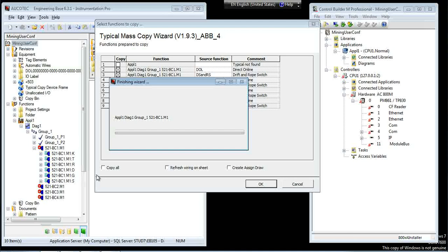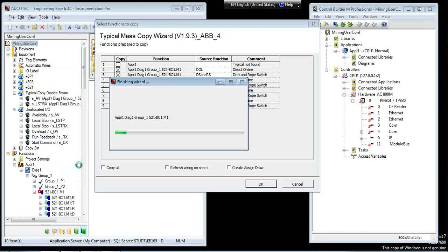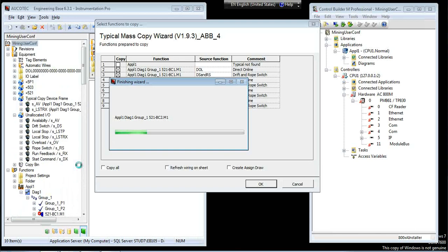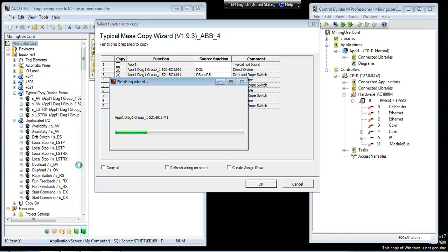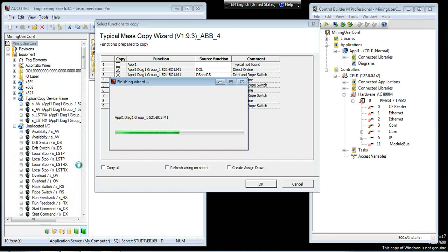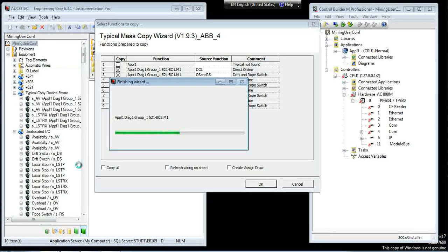its signals. So a lot of information is now added into the database. This information is basically all the electrical components required for the functions. This is I/O signals, this is cables, this is wiring, this is local isolator boxes, the motor itself, local start, stop, push buttons, and so on and so forth. The time it takes is about 5 to 10 seconds per motor to create all this information.